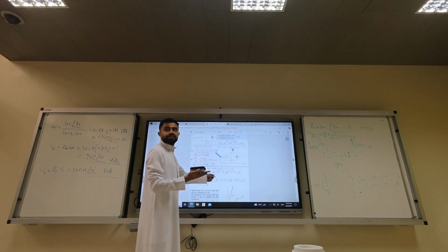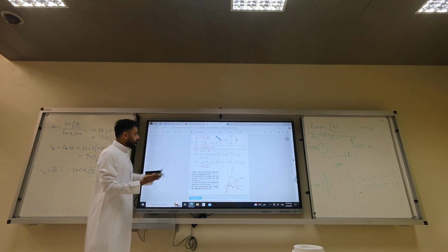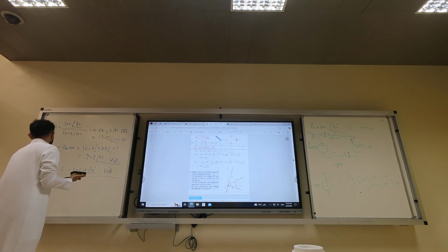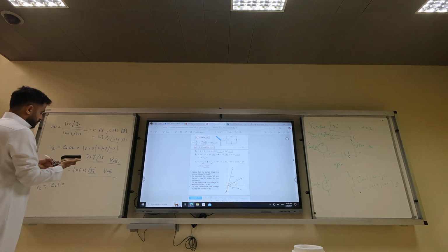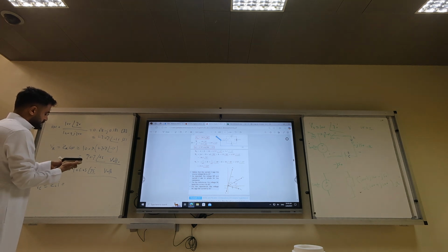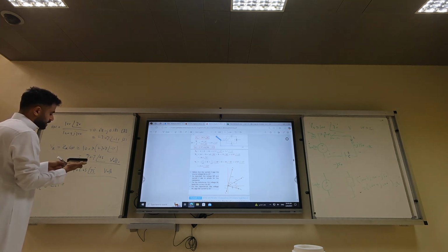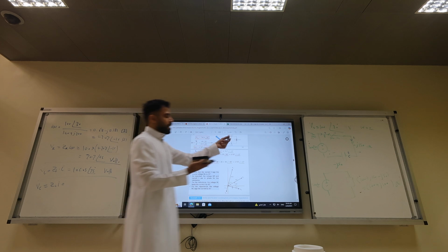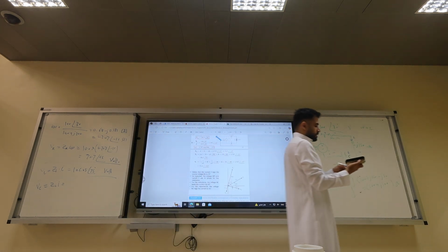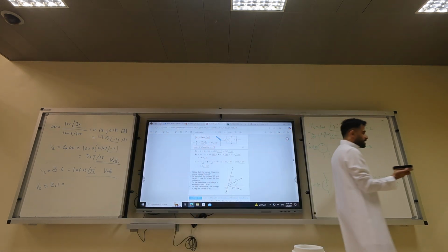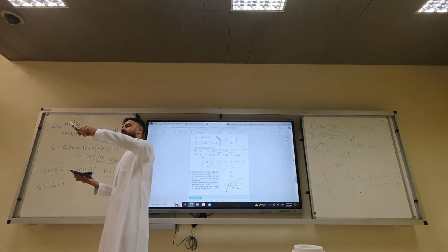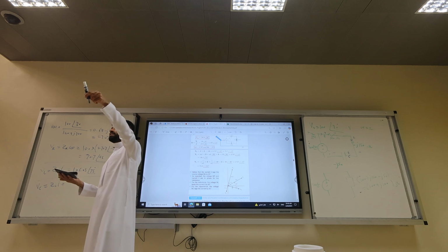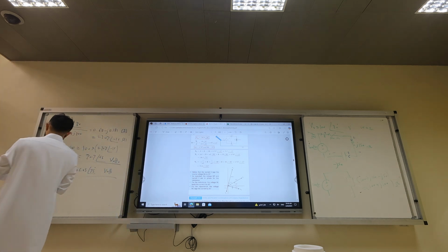106 angle 75. The last one is the capacitor. V sub C equals Z sub C times I, which is 0.707 angle minus 15 times minus J50. Don't forget the signs. You have to multiply by minus J50, not minus J50 times minus J50.